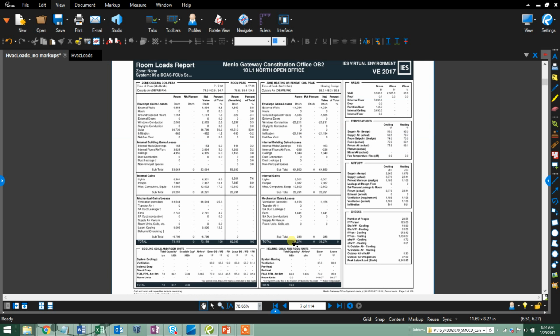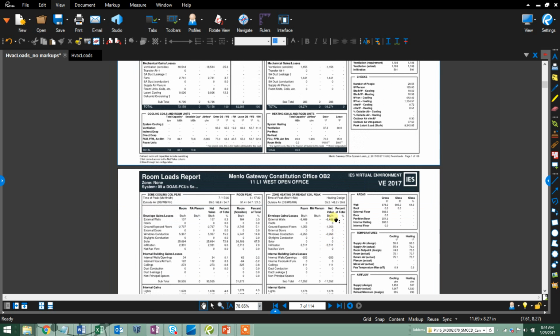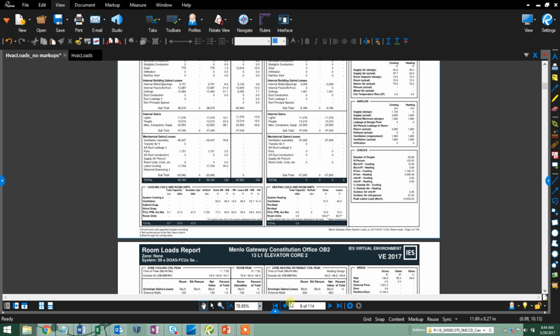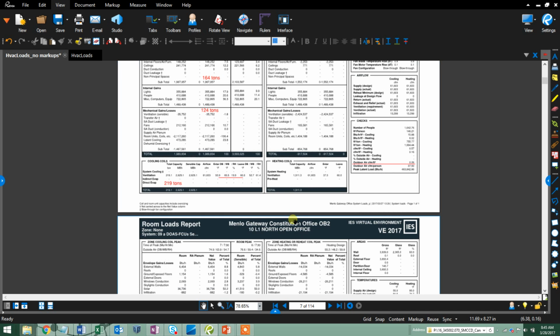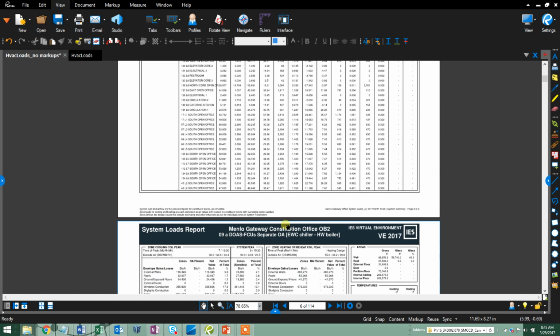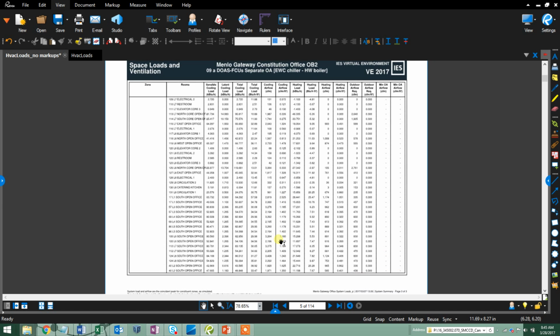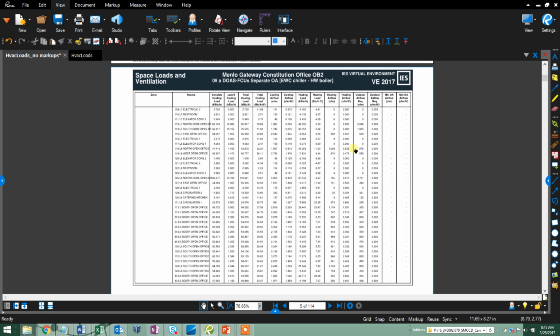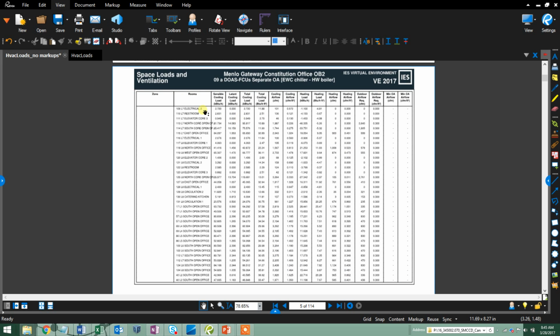The rest of these pages are the individual room loads and their fan coils and what drives the size of that fan coil. I would, at this point, not recommend going through these if I am only checking the whole building's load. The pages I did skip over would be a faster way to check each room to then pick out the problem children to review. And so really quickly, what do I mean by that?